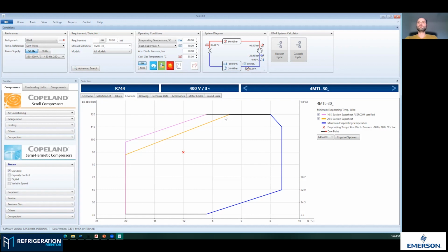As you go to the left, typically the discharge temperatures are rising because with higher compression ratios, there is a bigger temperature difference on the discharge of the compressor given by the thermodynamics. You also have less and less mass flow going along the motor, so the motor is less cooled. So the motor is getting hotter.